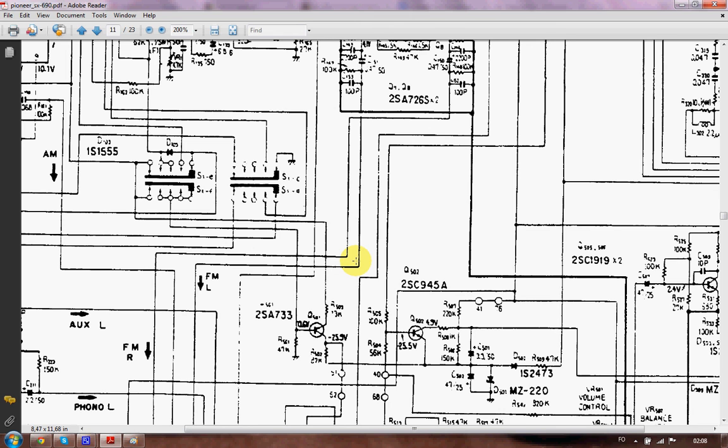And if there's only one channel that works throughout, as I said, throughout all the applications, AM, FM, auxiliary, phono, there's going to be most likely a fault in one of the amplifier's channels, one of the amplifiers on either channel, on the fault channel of course.